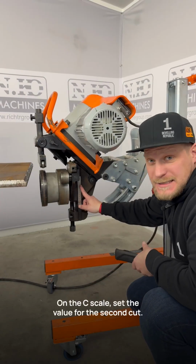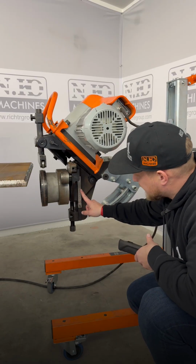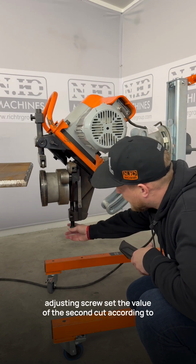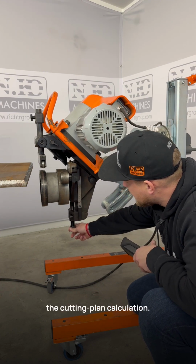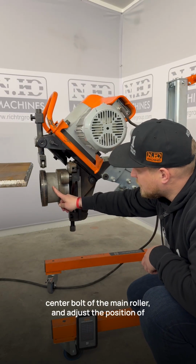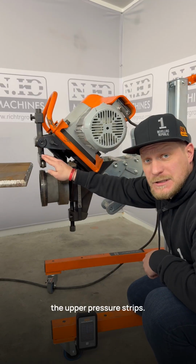On the C scale, set the value for the second cut. Loosen the center bolt of the main roller, and with the adjusting screw, set the value of the second cut according to the cutting plan calculation. Don't forget to secure it with a lock nut, retighten the center bolt of the main roller, and adjust the position of the upper pressure strips.